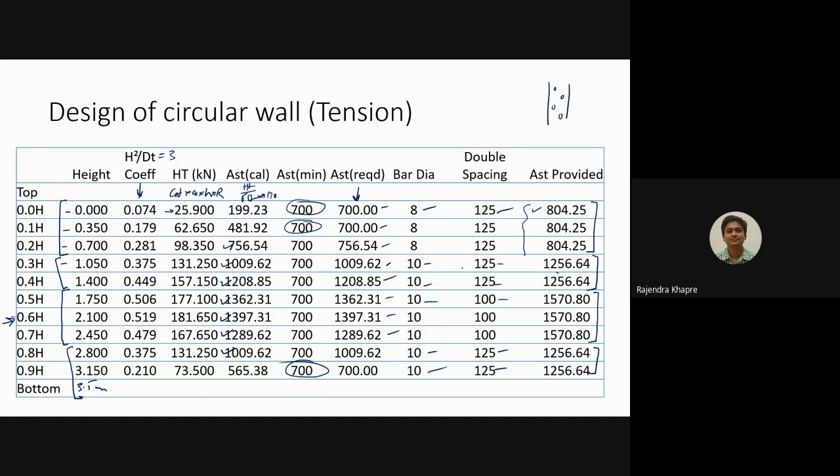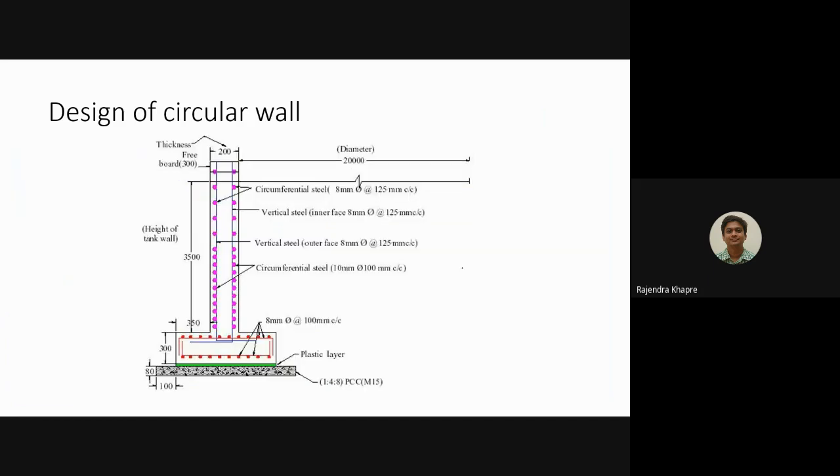You can use even this for the GSR also, especially in case of greater depth. If it is 1 or 2 meters, it does not make a difference, but if it is having a greater depth, in that case you can divide the entire region into different portions, and accordingly you can provide the steel so that the amount of steel can be saved over here. Okay. So I was talking about this.